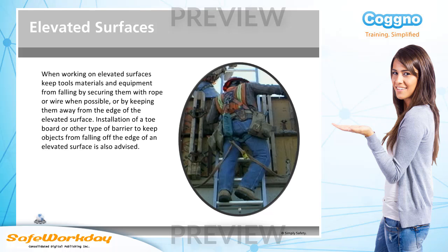When working on elevated surfaces, keep tools, materials, and equipment from falling by securing them with rope or wire when possible, or by keeping them away from the edge of the elevated surface. Installation of a toe board or other type of barrier to keep objects from falling off the edge of an elevated surface is also advised.